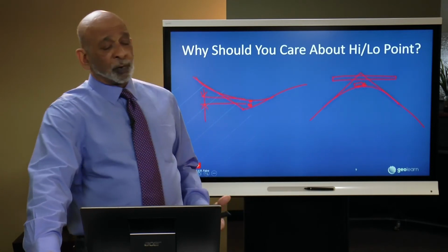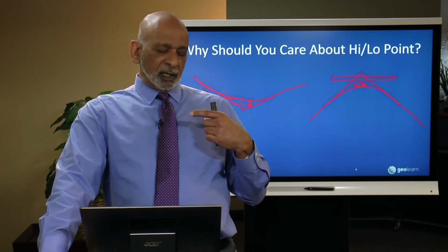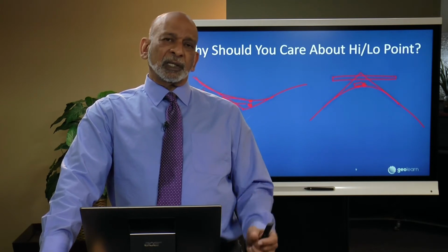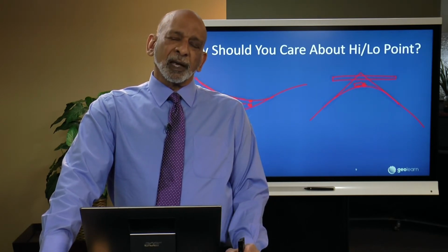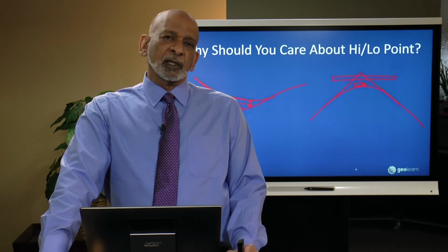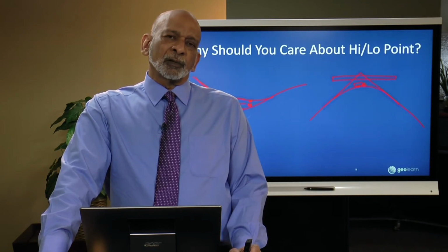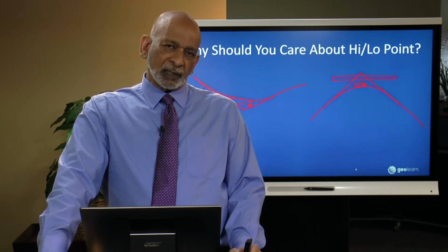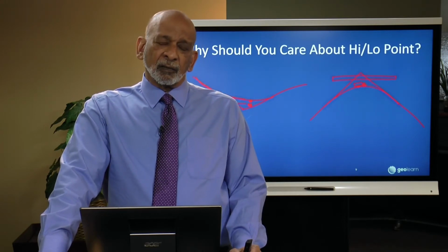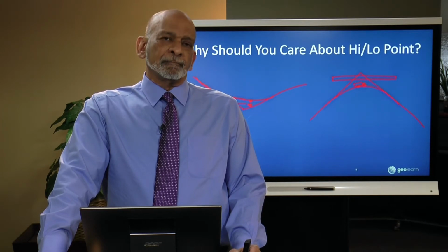It's probably a good time for me to just mention that quite a few times surveyors will discover mistakes made by others. That could be a contractor, an engineer, or an architect, where they assume something, and the surveyor goes out and tries to lay out the structure, because that's the first realization of the design in the real world, and will sometimes discover that things aren't working.